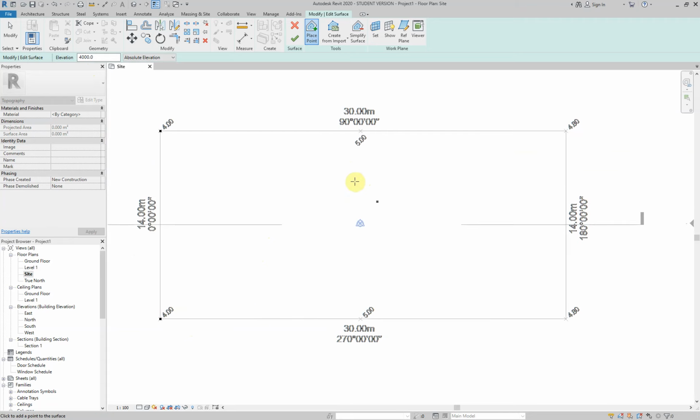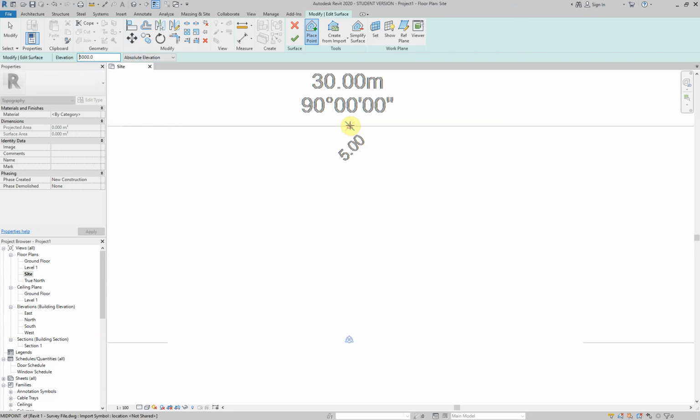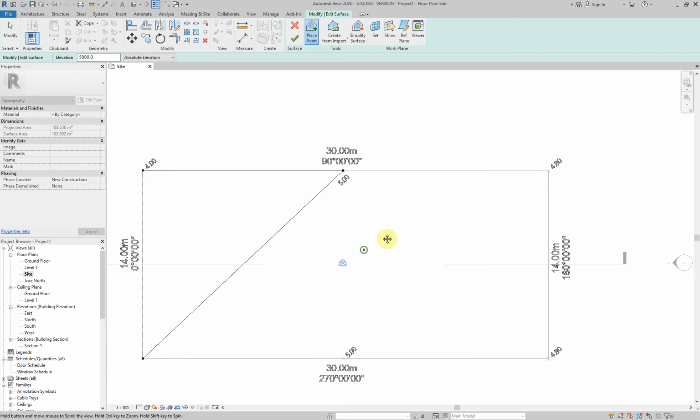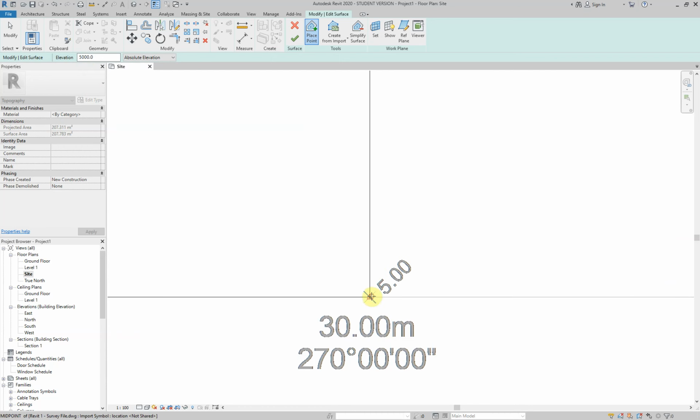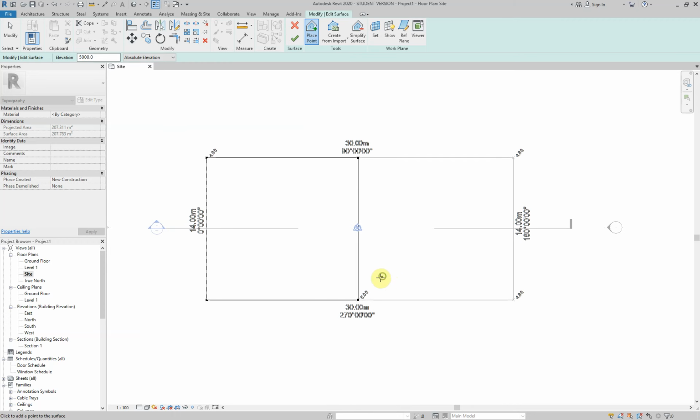Right. So I'm panning and scrolling. Now these ones here, it says 5 meters. So I come back up to here, I change that information, enter. It's now 5,000 millimeters, which equals 5. So I'm going to click there. Okay, 3 points, 1, 2, 3. I can now make a shape. Revit does that for me. Left click there, 5 meters.